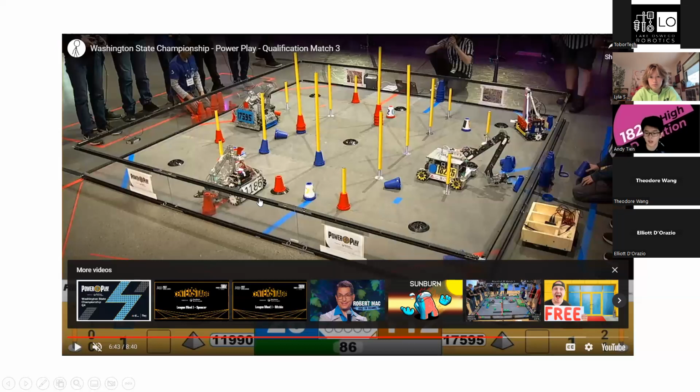Basically what ended up happening was, since the camera was not looking down to find the pole, it was looking kind of sideways. On one side of the field, you saw that we had purple and yellow spotlights, so that interfered with our computer vision, and that was part of the reason why our robot would be very slow at delivery. The second one is damage to the arm from people running into it. That was certainly a concern going into states.